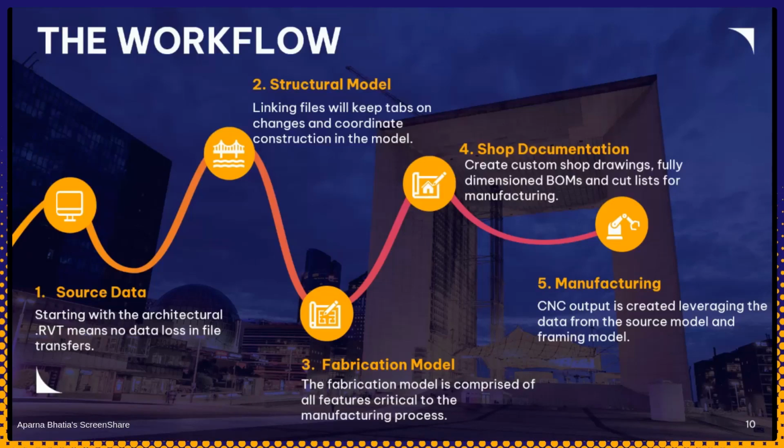Which makes your bill of materials and cut lists the most accurate because it actually considers the full length of the stud intersecting with a track and so on and so forth. This is also helpful for manufacturing, for when it does go into manufacturing for CNC outputs, you can catch the changes or the issues right when you're working in the model because you can see how all the members are connected. And you can push it up to our cloud-based platform called Onyx to create your CNC outputs and leverage data from our source model.